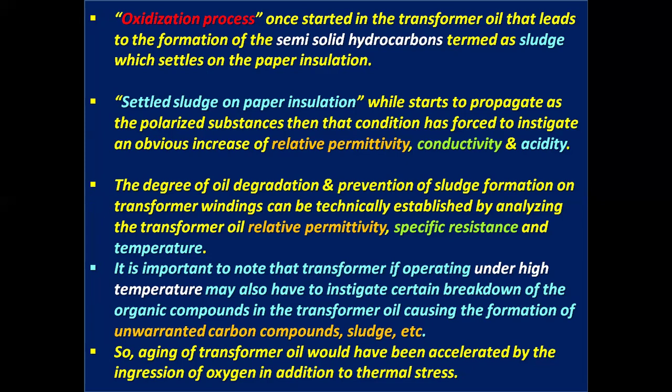The degree of oil degradation and prevention of sludge formation on transformer windings can be technically established by analyzing the transformer oil relative permittivity, specific resistance, and temperature.